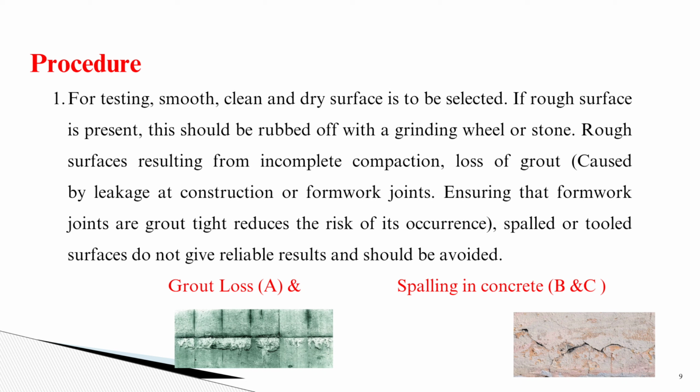Now, spalled surface is usually caused by water damage, freeze-thaw cycles or chemical reactions. Spalling of concrete can expose the steel reinforcement and lead to further deterioration. Now photo A shows grout loss and photos B and C show spalling in concrete, that is, reinforcement is exposed.